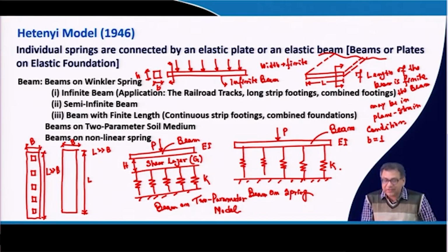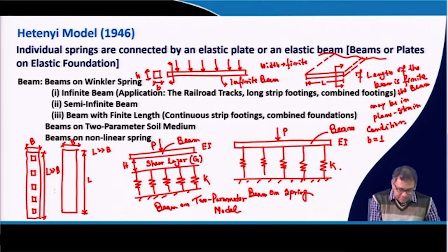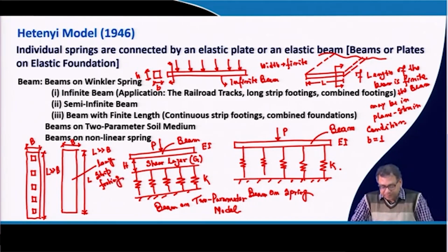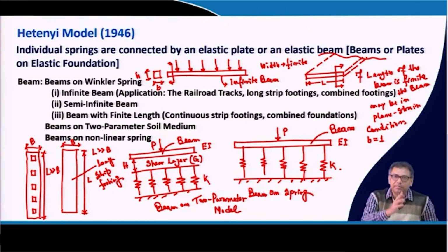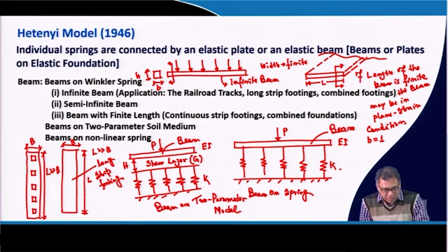But if you have a long strip footing like this case, this is a long strip footing. This can be modeled in two ways. One is, suppose the length of this footing is considered as the length of the beam. In that case it is an infinite beam, and the width will be the width of the foundation. This is one way.